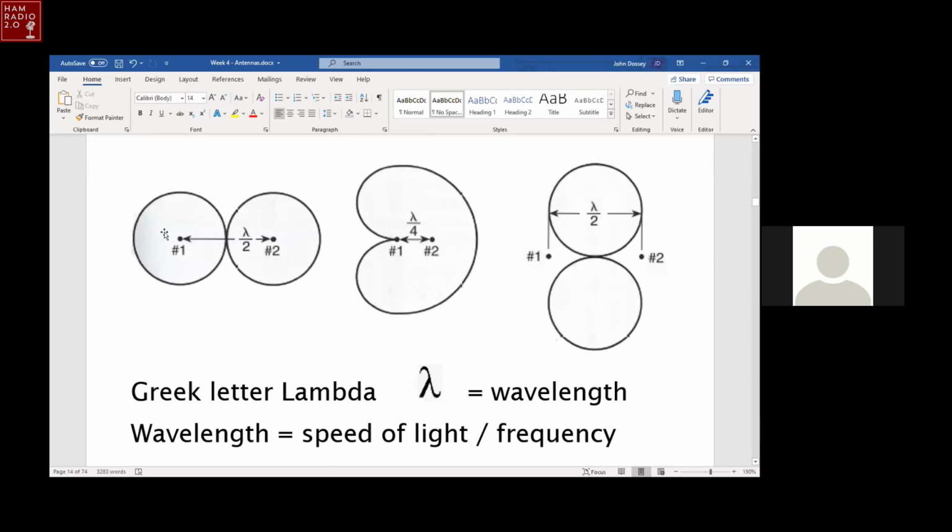So if you have an interfering station that's off over here, you call that west, up north would be up. So west of you is a big interfering station, like we used to have high-powered foreign broadcast AM stations right in the middle of the 40 meter band. You would point that null of the cardioid over here toward that station and really reduce his power that's coming into your receiver.